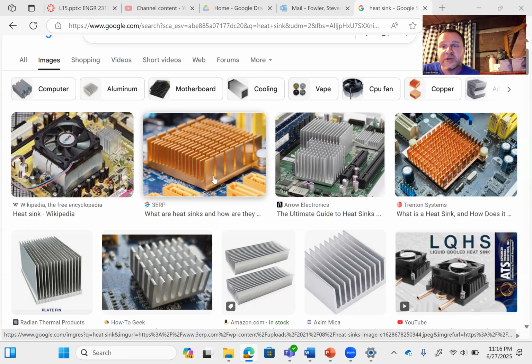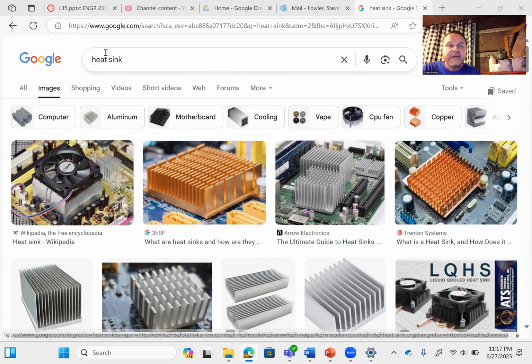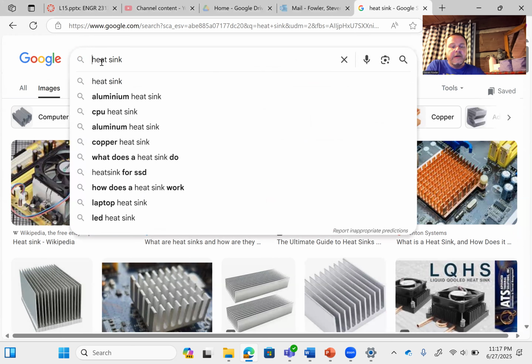You know what that means for the change in temperature. It goes up very quickly. Well, these electronic devices, if they get too hot, they don't work. You let the magic blue smoke out, so to speak. So what do we have to do? We have to keep these things cool. A heat sink is a piece of metal that is very carefully shaped in such a way that when we blow air through these fins using a fan, those fins are a pretty good shape at conducting heat away from these sensitive electronics.